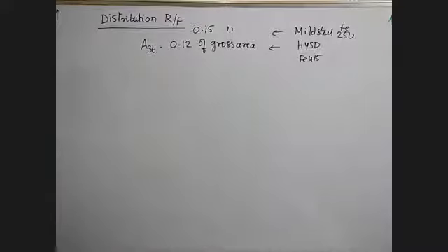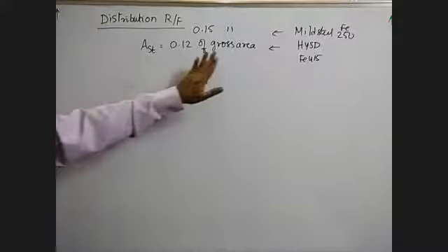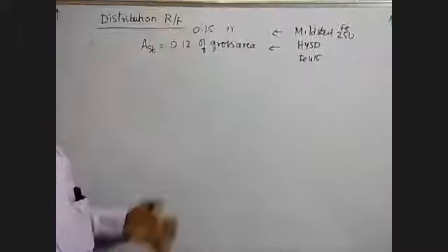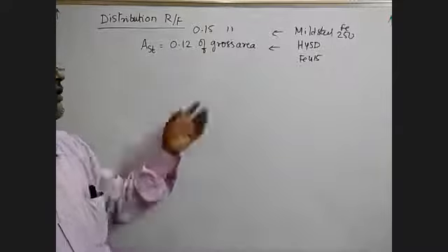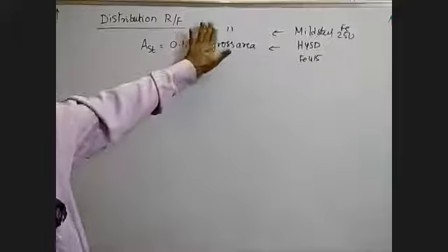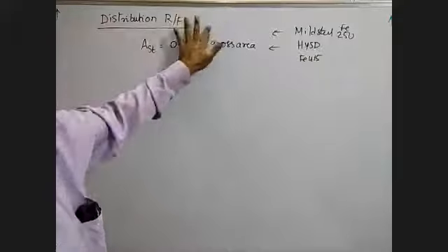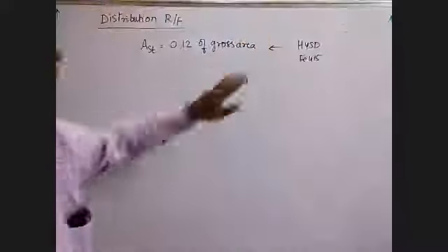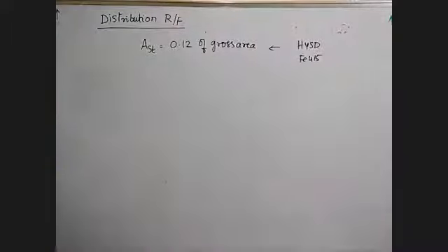అదొకటి డిఫరెన్స్ చూసుకోండి. క్వశ్చన్ లో ఇచ్చేటప్పుడు జనరల్ గా మనకి HYSD నే ఇస్తాడు. మనకి ఎప్పుడన్నా మైల్డ్ స్టీల్ ఇస్తే యూ హావ్ టు టేక్ దిస్ యాస్ 0.15% ఆఫ్ ది గ్రాస్ ఏరియా. మీకు ఇంటర్వ్యూ కానీ ఎగ్జామ్ కానీ వెళ్ళినప్పుడు స్లాబ్ లో మినిమం ఏరియా స్టీల్ ఎంత ప్రొవైడ్ చేస్తారు అన్నప్పుడు సమ్ టైమ్స్ దే మే ఆస్క్ యు దిస్ క్వశ్చన్. Okay, mild steel it is 0.15%. Now our problem it is Fe415 HYSD bars, high yield strength deformed bars. HYSD అంటే ఏంటి, రిబ్స్ ఉంటాయి. Mild steel and plain one.